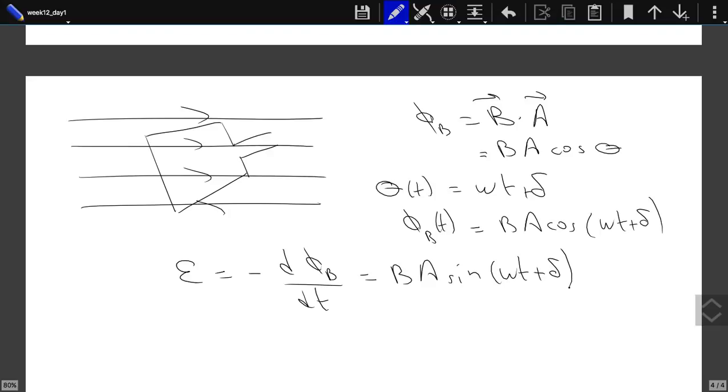So what you should do if you want to keep this rotating is, let's say you started here. When you reach this point, you should change the direction of the current, so that the magnetic dipole will be pointing in this direction, and hence, as it's trying to align with the magnetic field, it will keep rotating. Now, how can you change the direction of the current? Either use brushes in a DC motor, a direct current motor, or use an AC current. In that case, you should match the frequency with the rotation frequency of your motor.